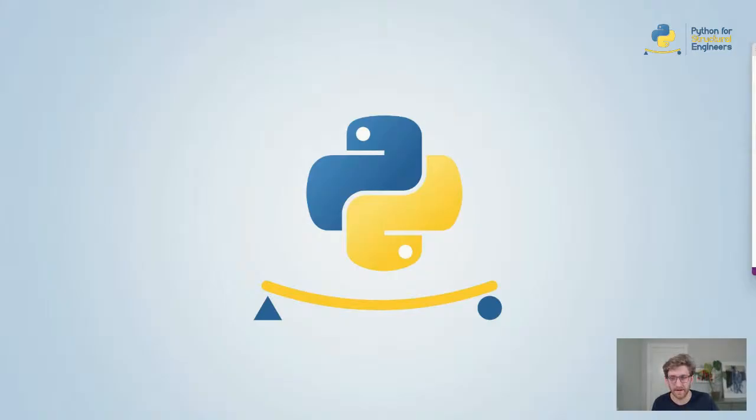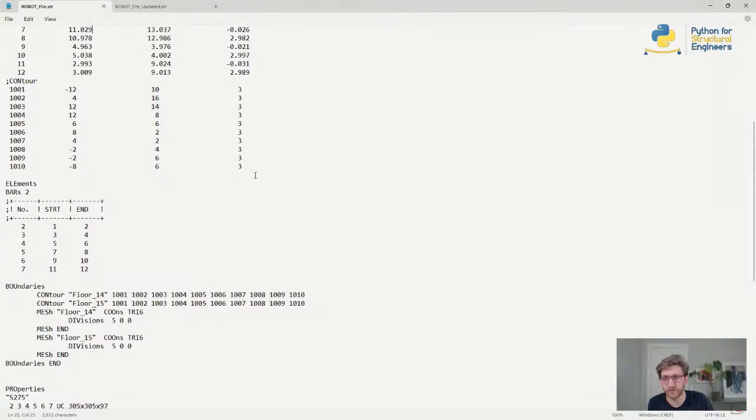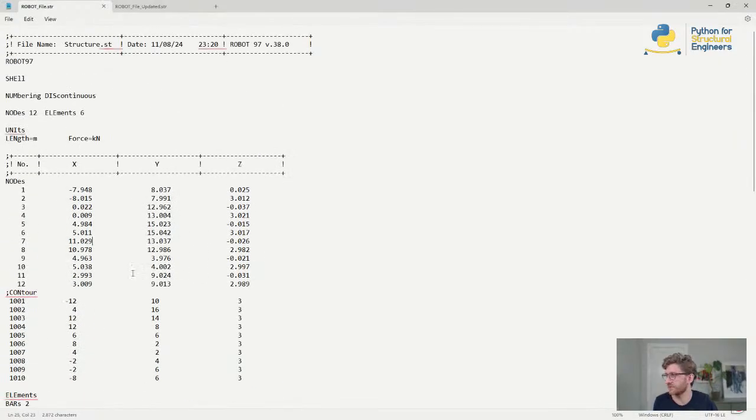The next example is to do with finite element models. Many finite element models can be defined with text files. So you can export your finite element model as a text file, then you can change that text file and you can import it again. So let's say we have this file here. This is from Autodesk Robot. And it's just a dummy file, like super simple. But you can see I have all the X, Y, and Z coordinates here.